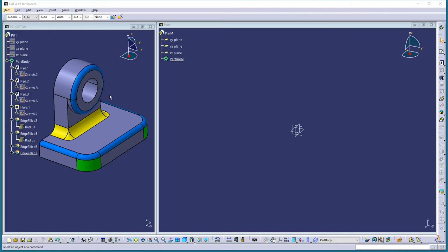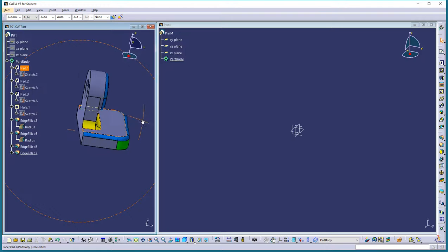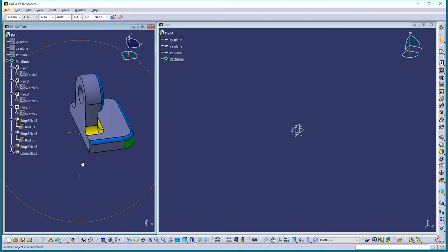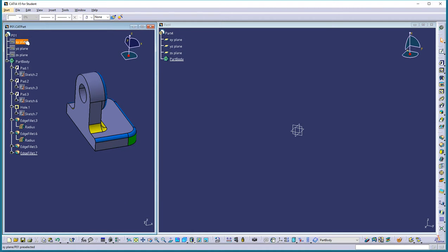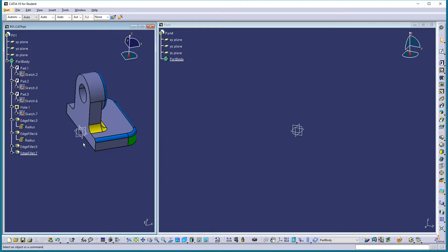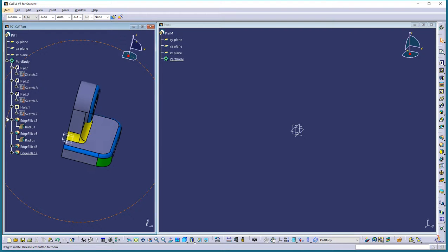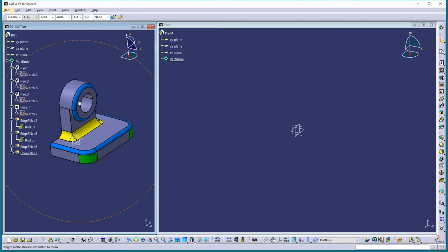Let's talk about how we would draw this part. First, we want to make sure that we pick a really good axis location. So let's see where they place the axis for this part. Let's do hide show. You'll notice right down here at the bottom, but it's on this back face, and the part is just centered right down the middle there. So now let's take a look and recreate this over on our model.